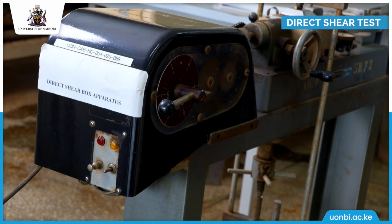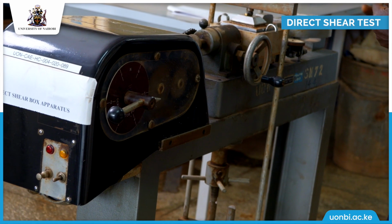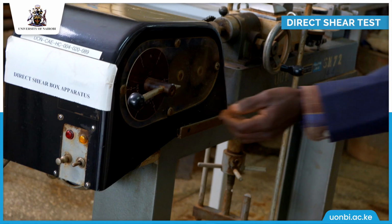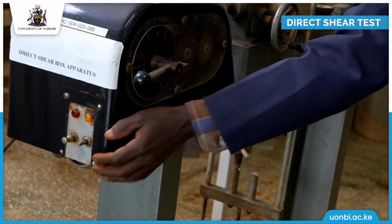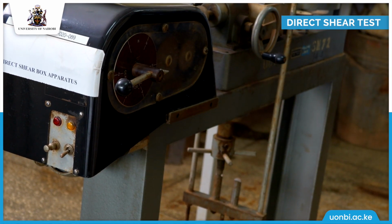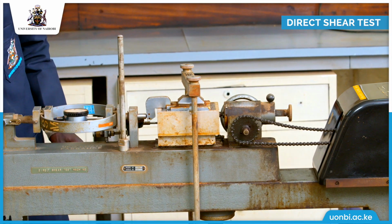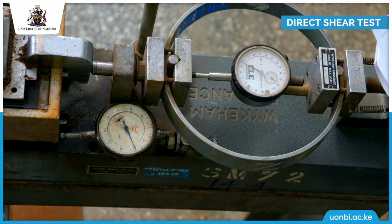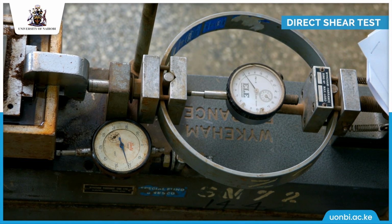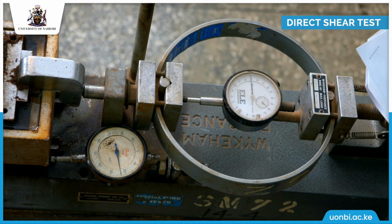I'm going to use intervals of 10 smaller divisions all the way like that until the sample shears. So I'm going to start the machine. I'm taking the second reading at 20 small divisions, which I have at 26.2.